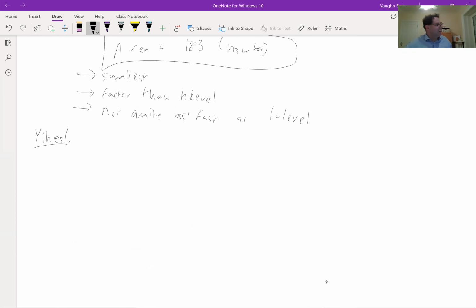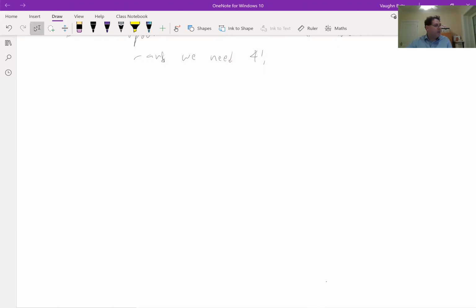Okay, but let's step back for a minute. This is kind of not a great story in terms of routing area. The LUT is what's doing our logic, kind of our computation. These routing muxes are just getting the signals there. So each one of these routing ports or input ports is close to a 4 LUTs area. And we need 4 of them. Okay, so that's a lot of area.